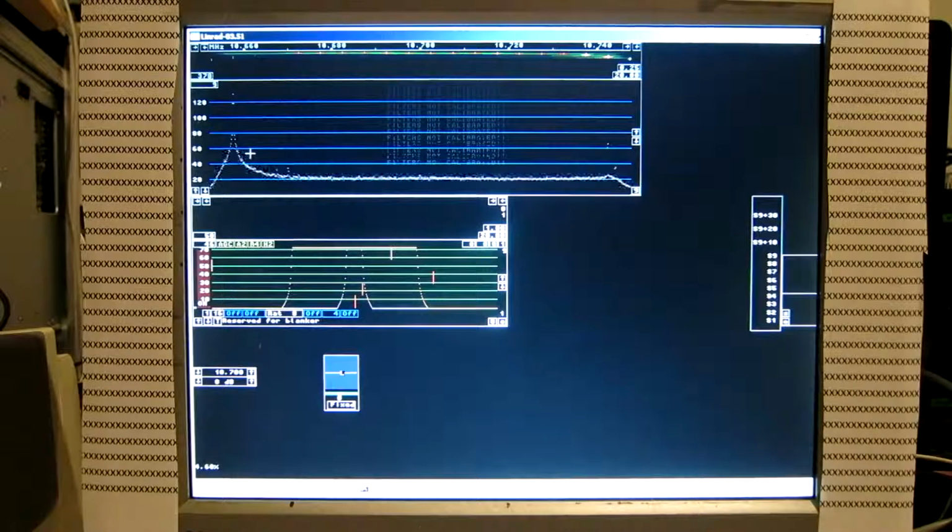And at the other end of the spectrum, we get a strong signal again. Well, strong and strong. It's now 130 minus 65. So that is 55 dB image rejection at the edge here. I think this is perfectly okay.